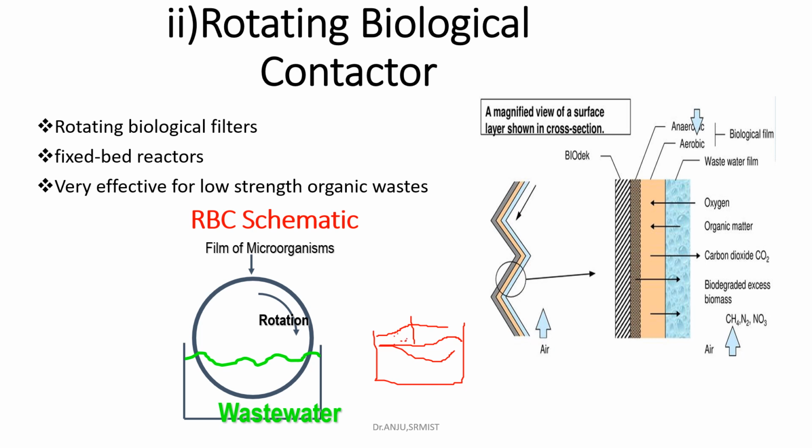In the case of rotating biological contactor, the media is rotated, submerged, and rotated through the wastewater, during which the microorganisms interact with the organic molecules in the wastewater. That is why it is called rotating biological contactor.